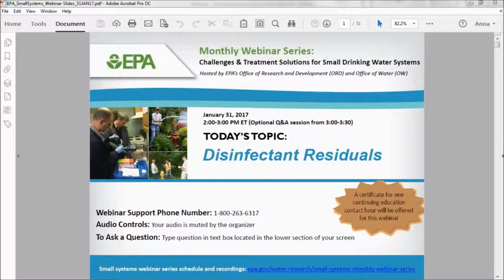And 11+, where does that throw you in terms of hypochlorite ion? It's pretty much all hypochlorite ion at that pH. At pH 7.5, you're about 50-50, and as you move one pH unit, at 8.5 you're 90-10, and at 9.5 you're 99-1. Only about 1% is hypochlorous acid in that range or higher.